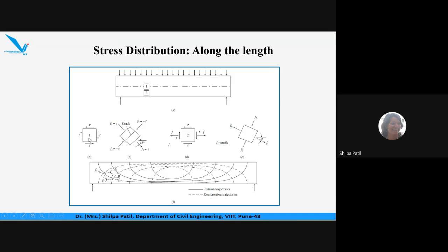If you take a piece of paper or any flexible material, hold two opposite corners in your hands and stretch them, tension develops along that diagonal, and in the other diagonal direction, there will be compression. So in this element, along this diagonal, there will be compression, and because of that excessive compression, a crack will get developed along this particular diagonal. Now if you consider this diagonal for this element, the crack will get developed at a 45-degree angle.